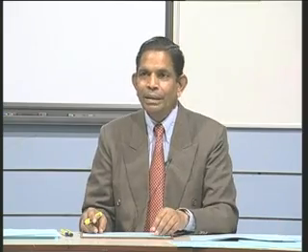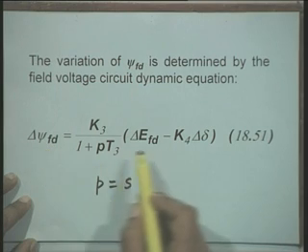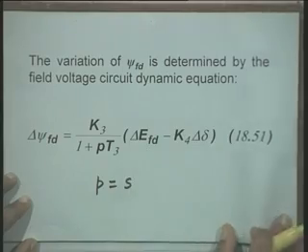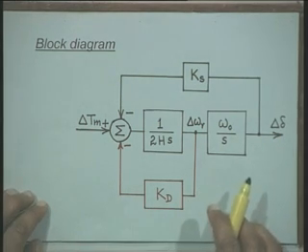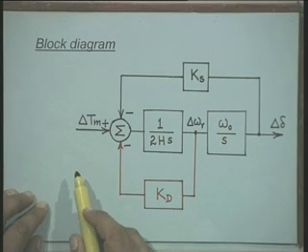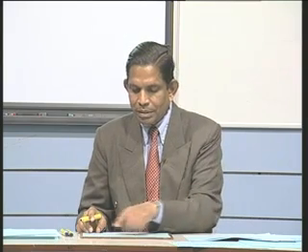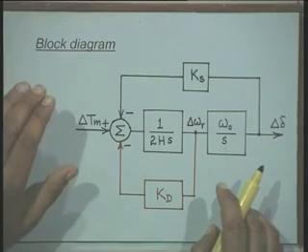Now, we will incorporate the transfer function relating the change in field winding flux linkages to change in rotor angle and field winding voltage. Earlier we had developed the transfer function model relating the variables considering the first two equations of the system. Now, to this model we will add the equation relating the field winding variables.